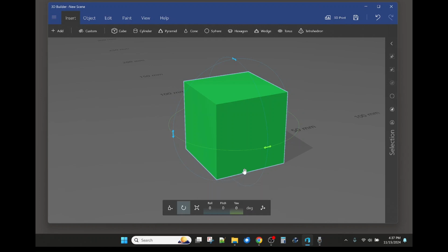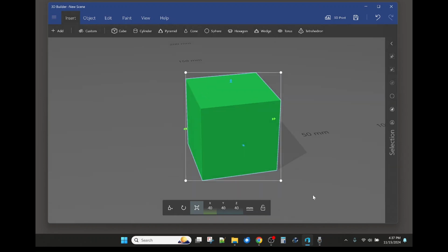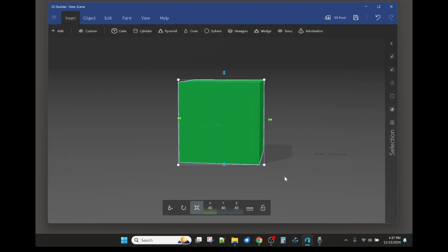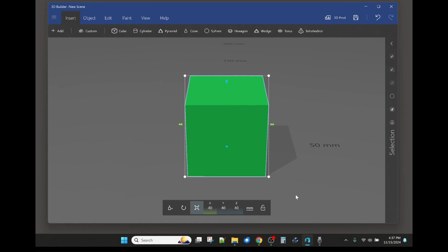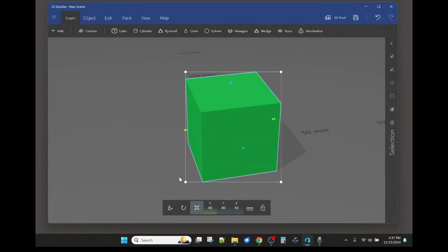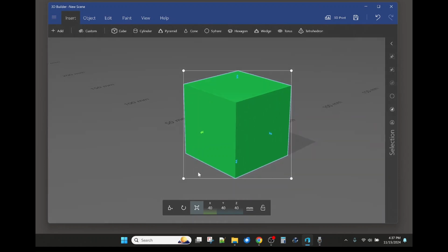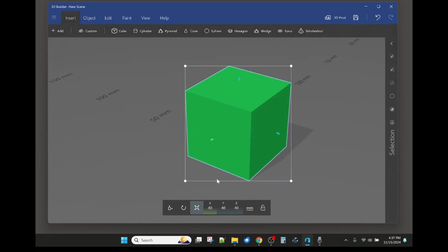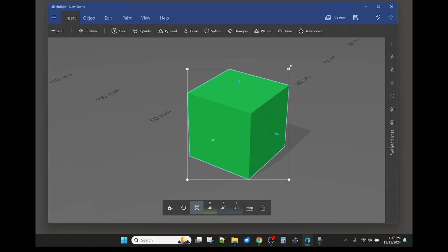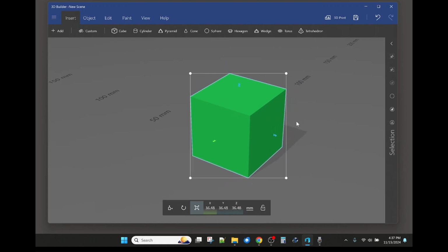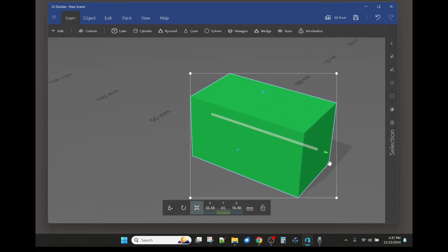The third tool is Scale, the only tool of the three to actually change the object's dimensions. The toolbar parameters go back to X, Y, and Z values, but now the arrow tools around the object are accompanied by a white rectangle around the object, which allows you to change the object dimensions in two directions at once. For our purposes, the arrow tools are the most useful. They allow one to grow an object in a specific direction, keeping the object's original placement.